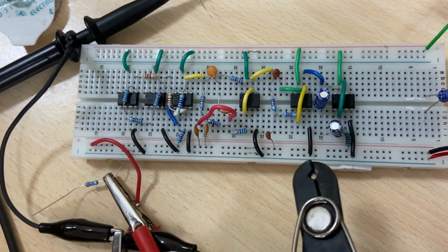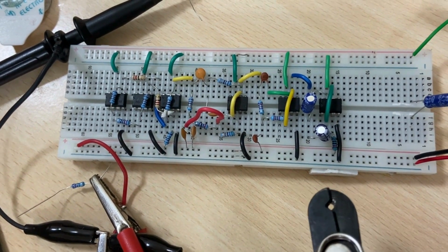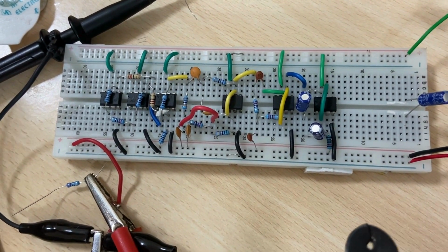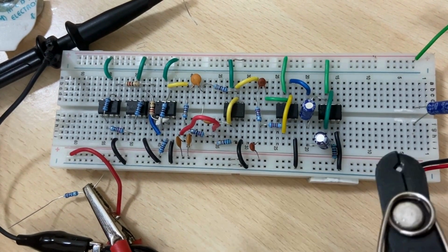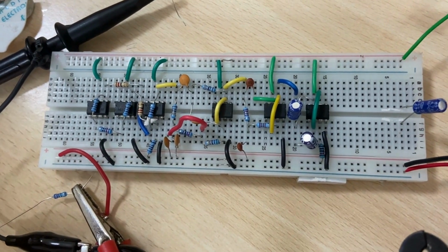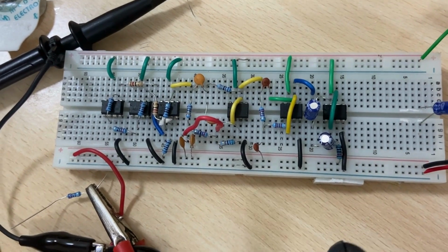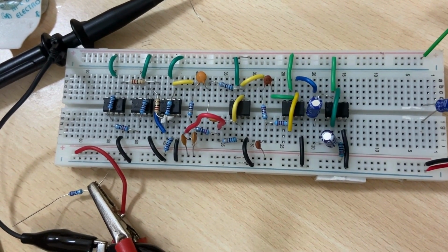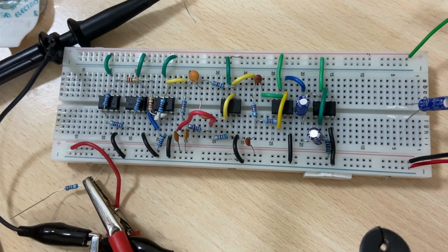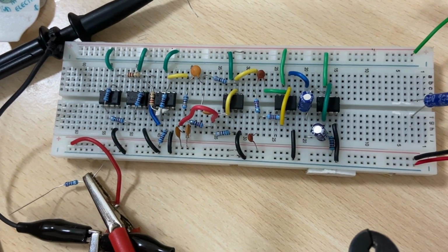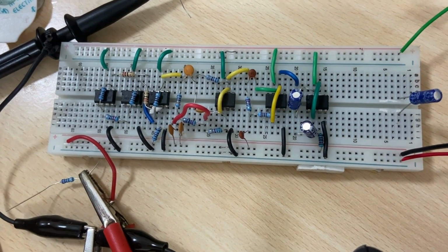The next stage after it is a low-pass filter. The low-pass filter is designed to cut off at a frequency of 150 Hz, which is being verified through simulations and also through FRA analysis on our circuit. Further, the last stage is a high-pass filter, which is supposed to block out the DC voltages coming from breathing and muscle movement. The cutoff frequency is set to be around 0.5 Hz. This particular set of frequencies was chosen keeping in mind the typical range of heartbeat values, the beats per minute, and also in order to preserve the particular spikes used for medical detections.